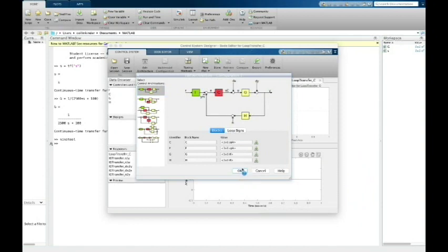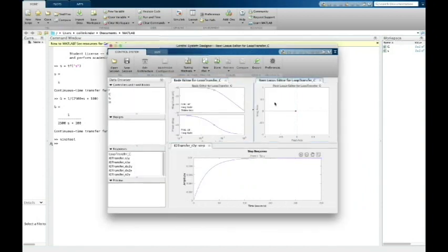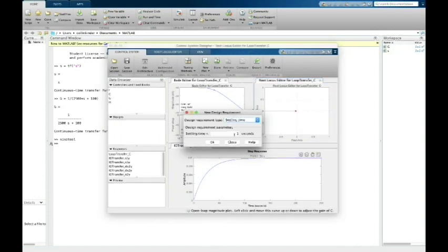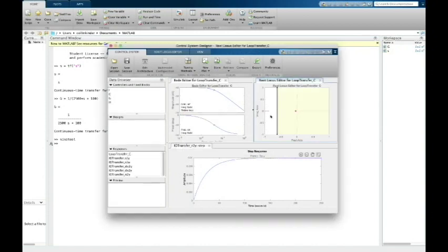In order to remedy this, we added a real left-hand plane zero to the root locus and began moving the zero and our open loop pole around until both were in the acceptable region. Our system now satisfied our time domain constraints set earlier. However, we essentially re-implemented a PD controller, and our gains were enormous and we had no phase margin.